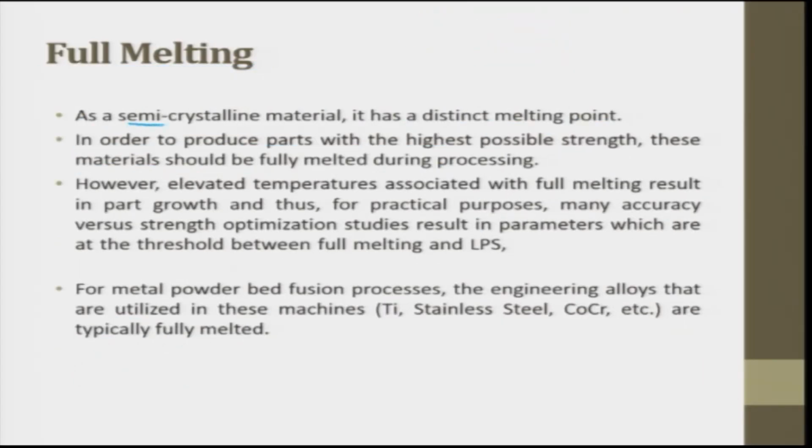As a semi-crystalline material, it has a distinct melting point. Crystalline materials have a distinct melting point, amorphous materials do not have. Semi-crystalline has somewhere in between. In order to produce parts with the highest possible strength, these materials should be fully melted during the processing.